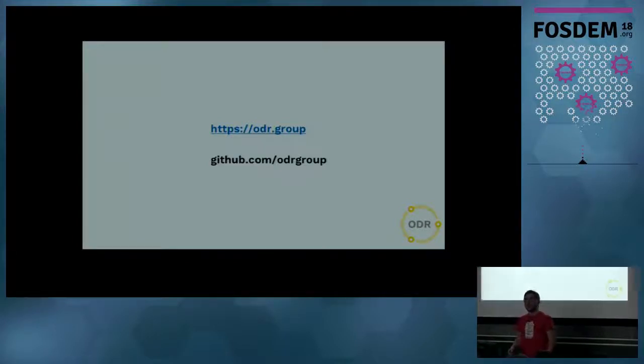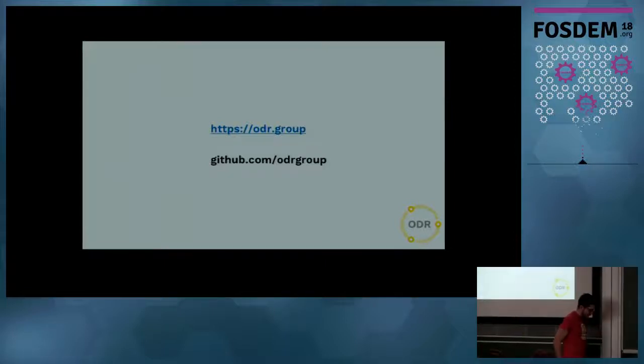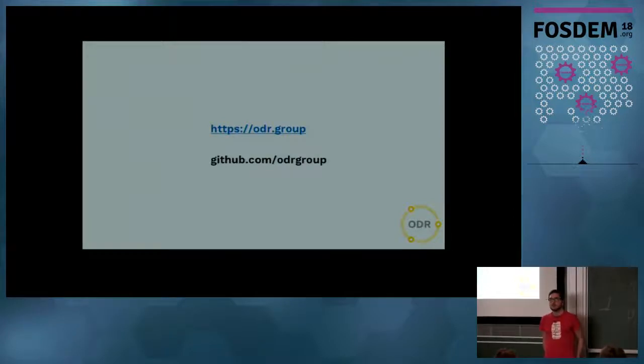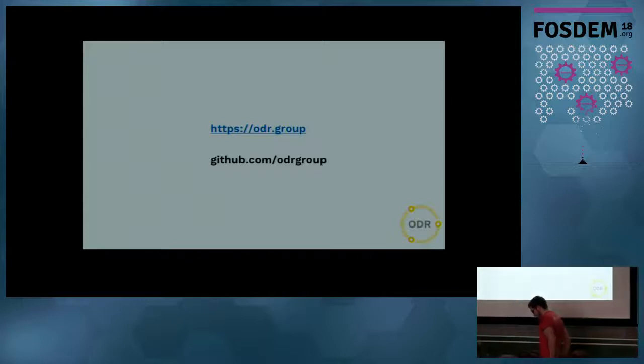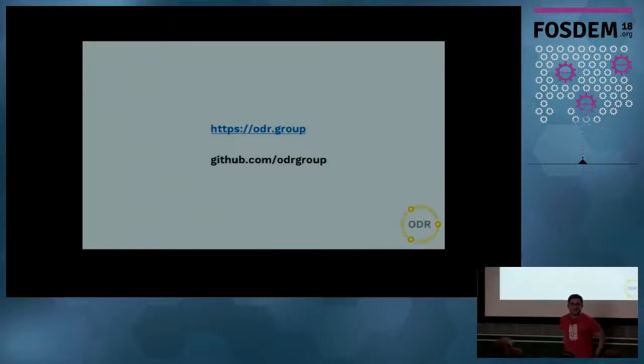Questions? Tom? I noticed that the file format you propose is very, at least judging from the example, very manufacturing oriented. What about typical design rules, especially more complex ones, concerning the topology of routing, signal integrity, different clearances for different parts, regions in the board? I'm asking because after the V5 of Cadence is out, we are planning to do a big overhaul of the design rule management system. And what you just proposed looks like a good candidate for the rule description format.